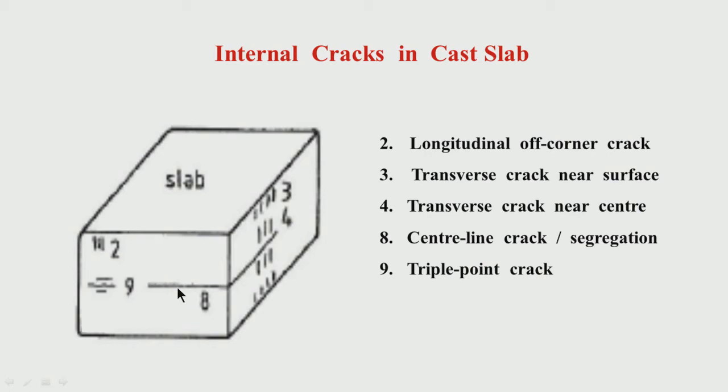Crack you will have if you have a relatively bad casting, then you have relatively coarse cast structure. So, your superheat was high. So, your columnar zone is extending from the surface to the center, then you have crack, you have a lot of segregation, it is a bad central area. So, superheat plays a big role here.